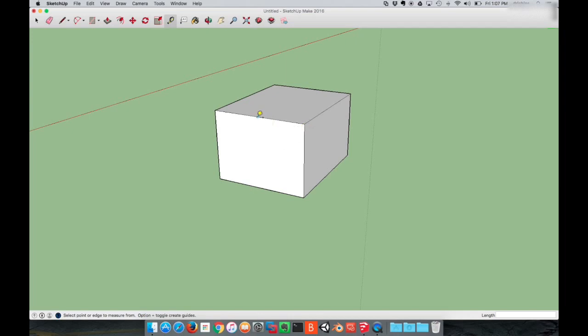I'm going to go to my midpoint, starting on a line, and just drag down. The dimensions box down there has now changed to a length box. And I'm putting this dotted line in with my tape measure tool 11/16 of an inch down. That line isn't actually part of the model, like what this line tool would draw.